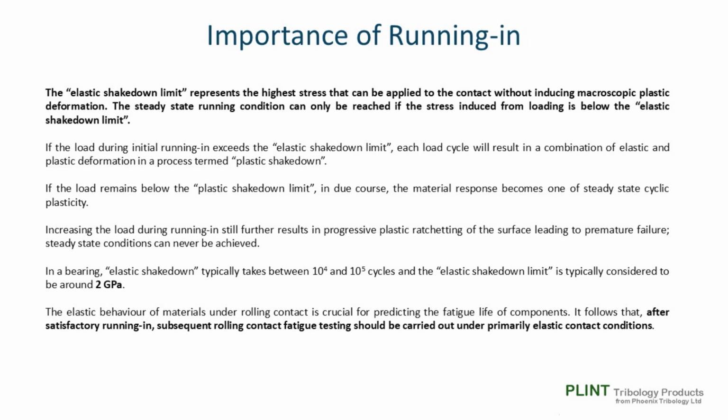If the load during initial running in exceeds the elastic shakedown limit, each load cycle will result in a combination of elastic and plastic deformation in a process termed plastic shakedown. If the load remains below the plastic shakedown limit, in due course the material response becomes one of steady-state cyclic plasticity.